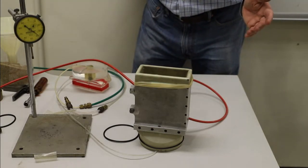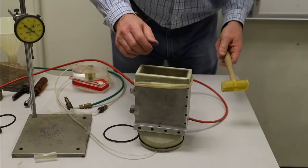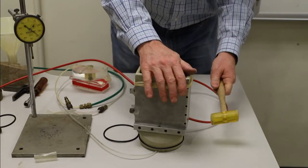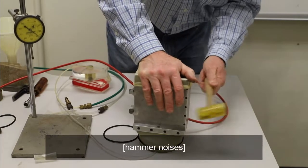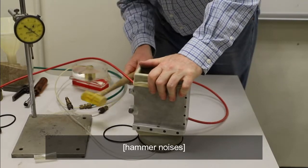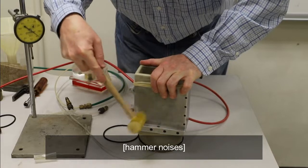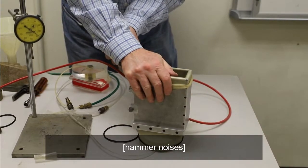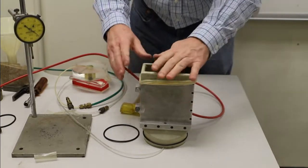The best energy to apply for densification is dynamic energy or cyclic energy, vibrational energy. So this is going to get a little bit loud, but we want to basically shake the sand particles into a dense configuration. Okay, so that's layer 1.